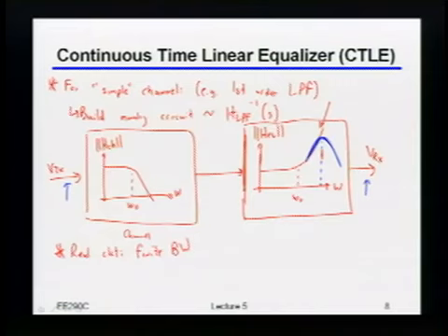Okay, so from the high-level standpoint, that's really all that's important in terms of continuous time linear equalizers. I'll just remind you briefly how you actually build them. Again, I'm hoping that most of you looked at this quite a bit in 240. If you don't remember, you can always go back and take a look at the videos there. But typically you'll build this on the receiver. The reason is that the impedances you're dealing with are higher at the receiver, so to get a certain voltage gain or signal swing, it usually takes less power than at the transmitter.